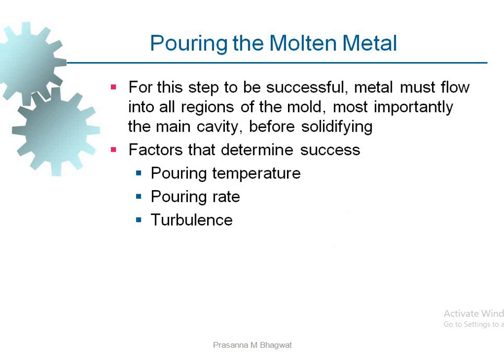Once the metal is ready, that particular metal is poured into the mold cavity. The factors which determine the success are the pouring temperature: what should be the temperature during pouring? What should be the rate of pouring? And whether it is providing any turbulence or not.